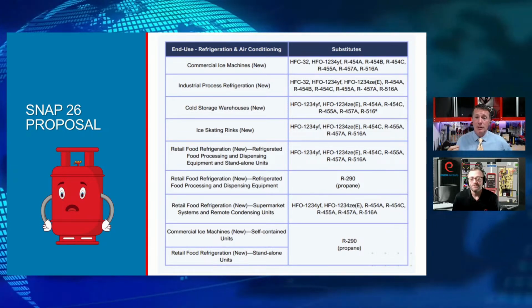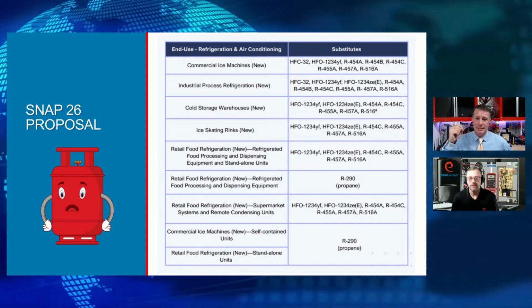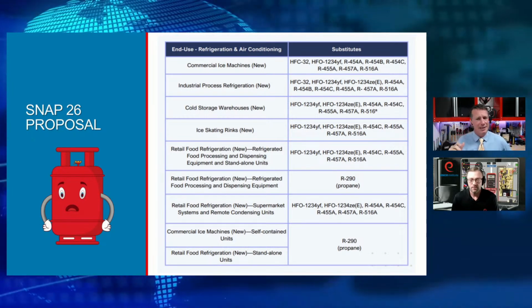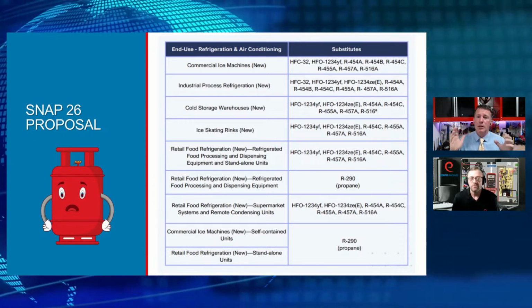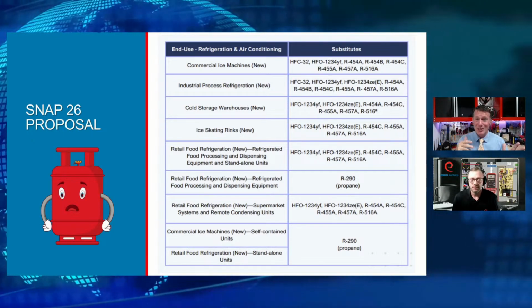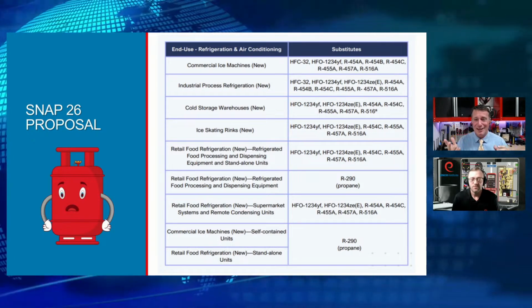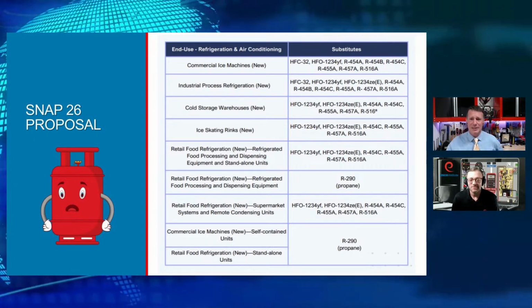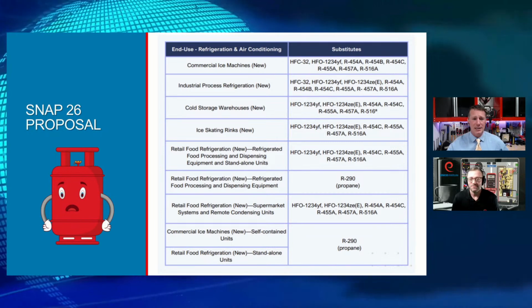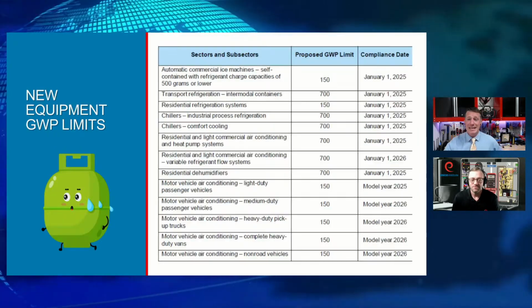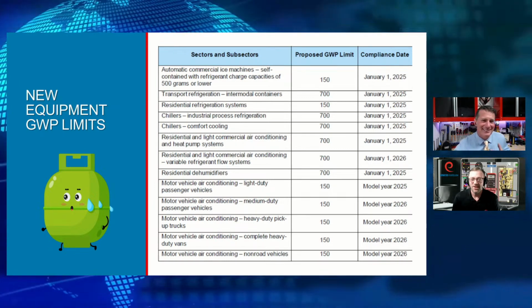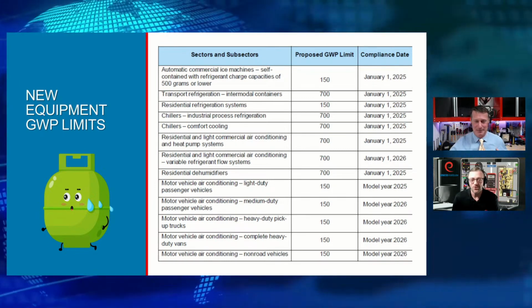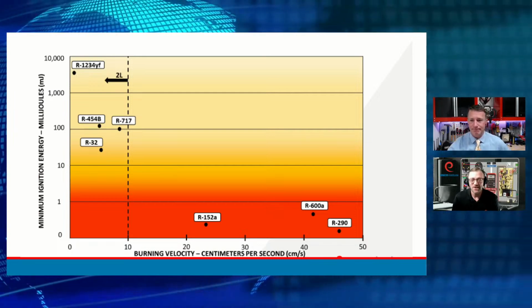And if we want to talk a little bit about the blends, like the 454s, we'll talk about that here in a minute. We'll come back to that, because even a lot of these numbers that you're not familiar with right now are blends of some of these other numbers, like R32 and 1234YF. A lot of them, yes. So we'll talk about those a little bit to give you a better understanding. I know no one hopped in there on the chat. I feel heartbroken. 410A and 407C were the two that got picked on the most there.